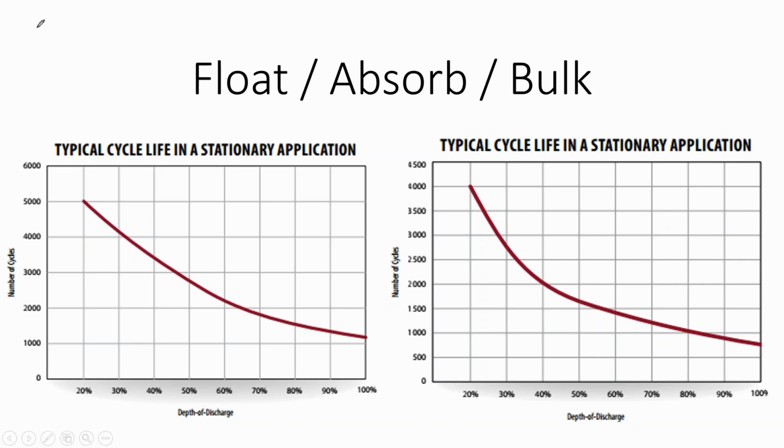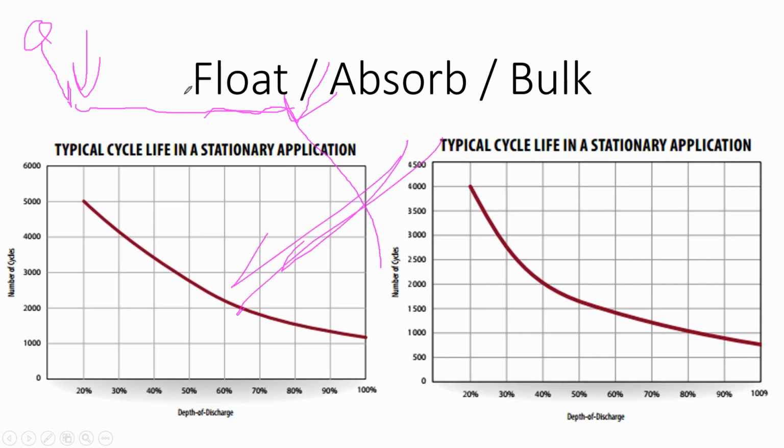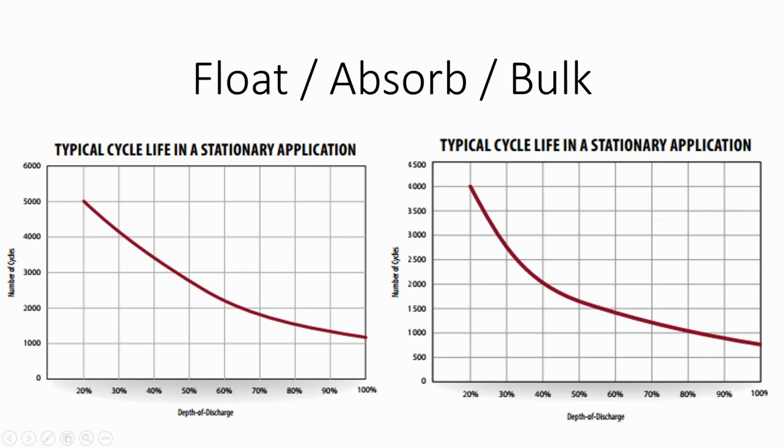So it's more like your battery that's fully charged is at 58 volts, but then it immediately starts to kind of discharge, and then it levels off at maybe slightly above 48 volts. And then as it begins to be fully discharged, it gets slightly below 48 volts, and then all of a sudden it's dead. If you had a granular monitor, you could be much more accurate at what point of state of charge you're at, but a simple voltmeter won't do.